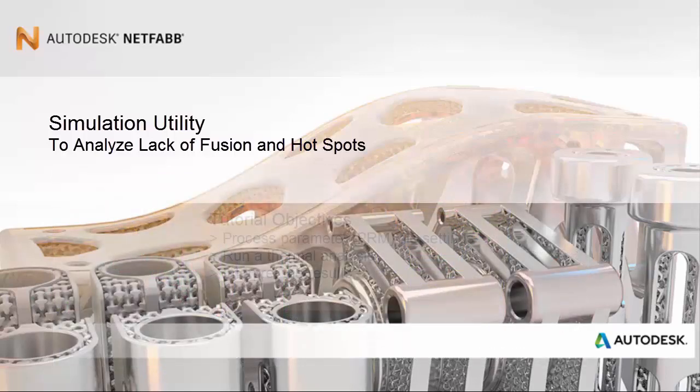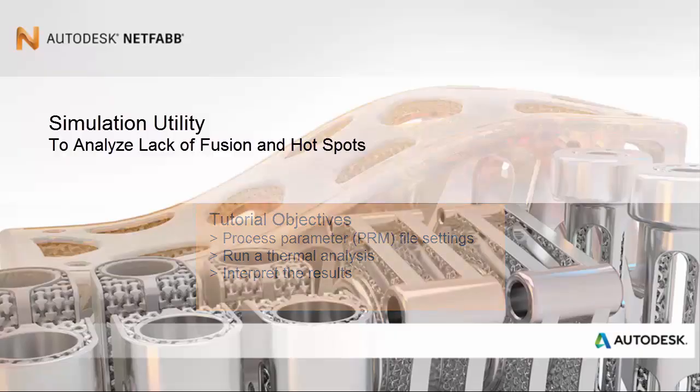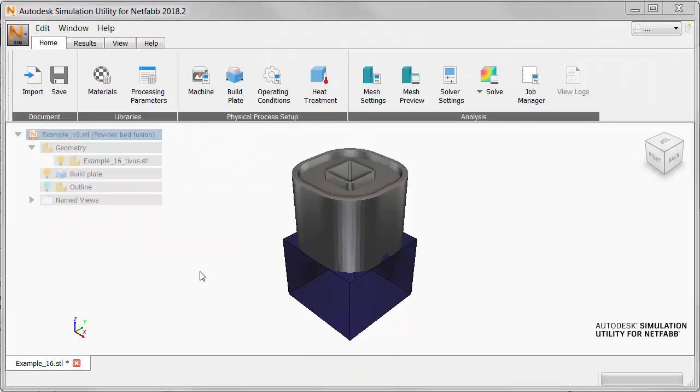In this tutorial, we will first discuss the process parameter or PRM file that supports this type of thermal analysis and the settings required. Then we will run an analysis at the part level and briefly interpret the results. To review the PRM file and its settings, on the Home tab, click Processing Parameters.